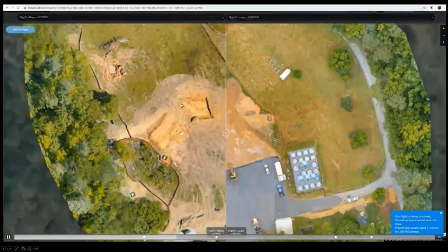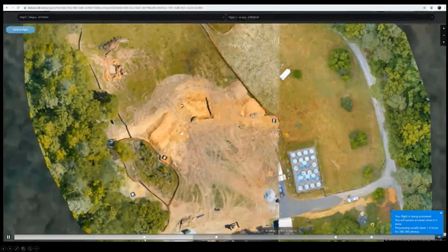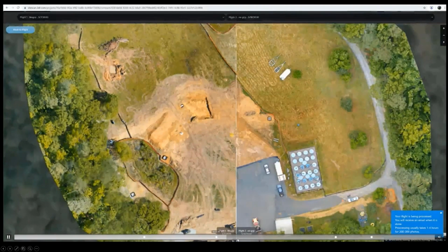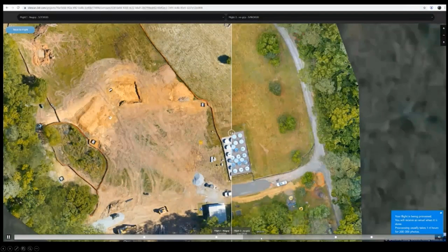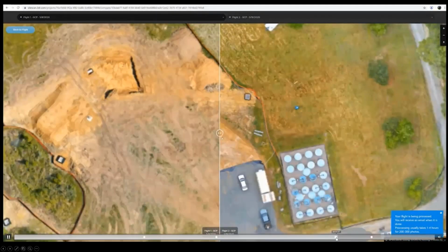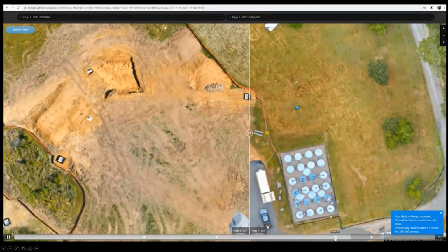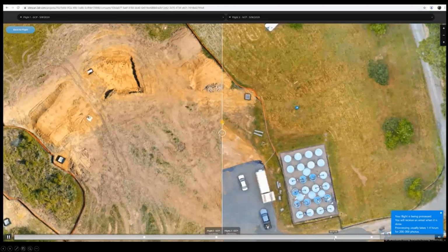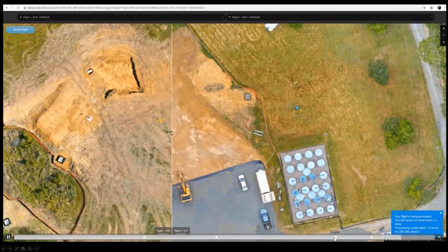And you can see here, this is without ground control. You can see these don't necessarily line up all that well. And so if I process this with ground control now, and move through here, now you can see that I've got my ground control in there and the two data sets overlap, and you can look at change between the 2 weeks, which obviously there was a lot of change between 2 weeks.